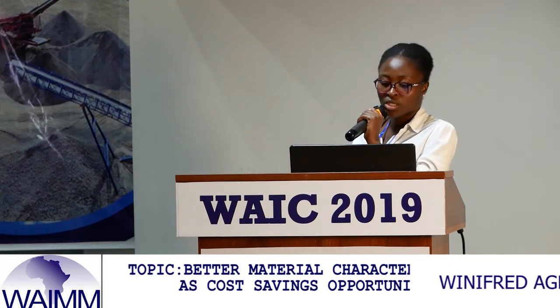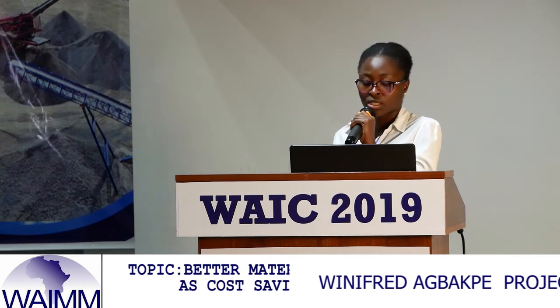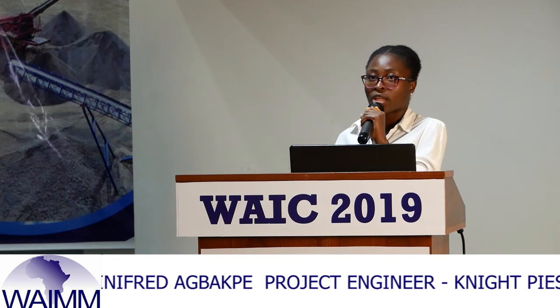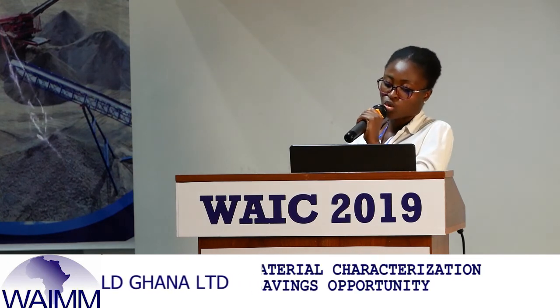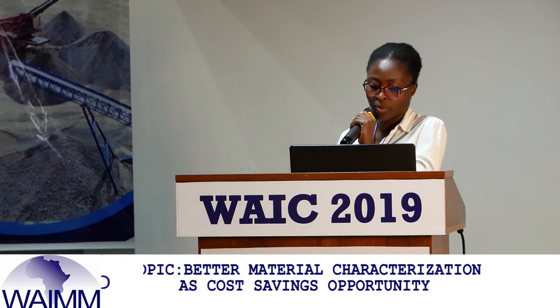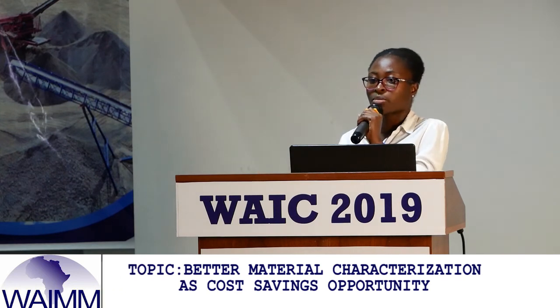Further investigation was done at the cost of $40,000. And based on that, they found that the fill material was strong enough and they could reduce the slope angle of the embankment. So instead of a 3-in-1 slope, they did a 2.25-in-1 slope, and they saved $1.8 million.